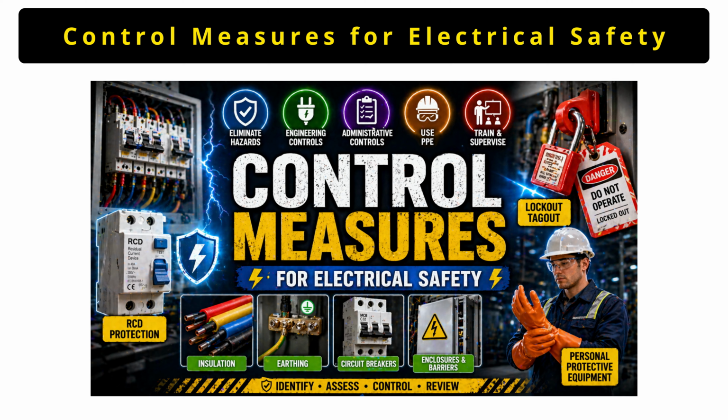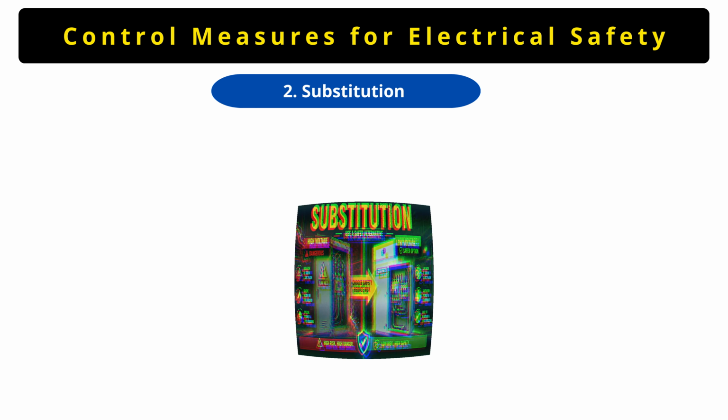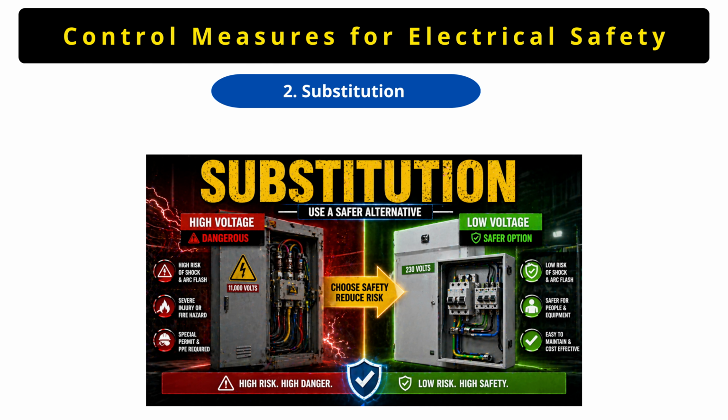Now let's talk about what are the control measures for electrical safety. Electrical hazards can be controlled using various methods. So whenever you have to take control measures, you have to follow the hierarchy. In the hierarchy, there are 5 steps. So the first step is elimination. Always try to do the first step. If the first step is not possible, then you can move to the second step. But focus on the first step, that is elimination, which means remove electrical hazards where possible. If that is not possible, then move to the second step, that is substitution. So you can use lower voltage systems.